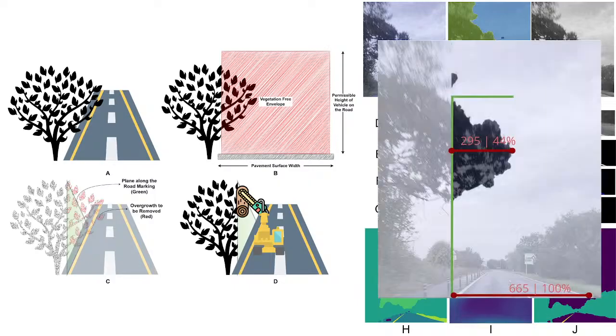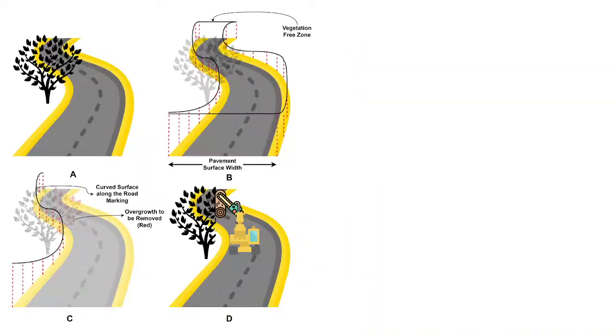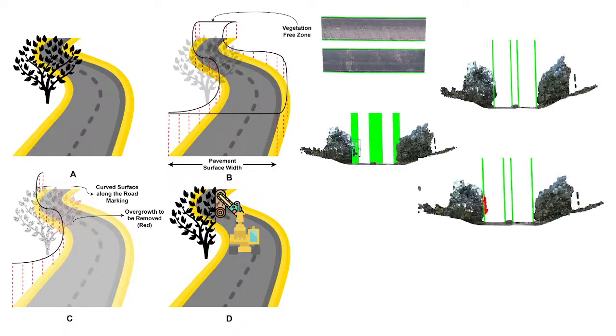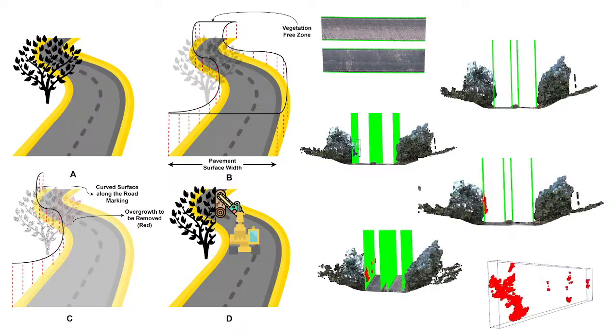Because it was just captured through a camera, there was no calibration, there was no ground truth available. We were able to just tell that if there is 100% of road width, around 44% of road width is there. Similarly, we went ahead with the 3D technology. We had a stretch, we have our dataset called the Cam Highways dataset, and finally here we were able to extract the 3D point cloud of the roadside vegetation.